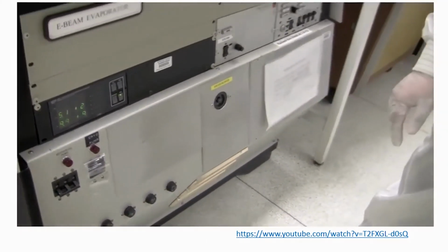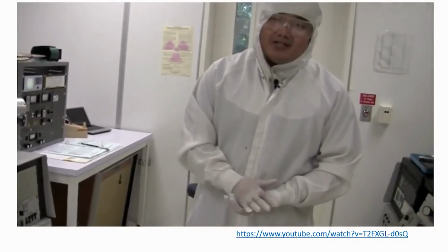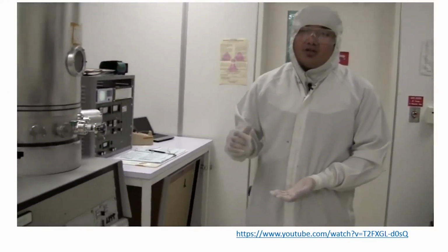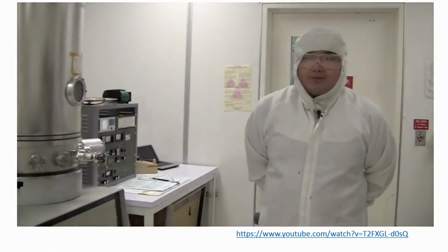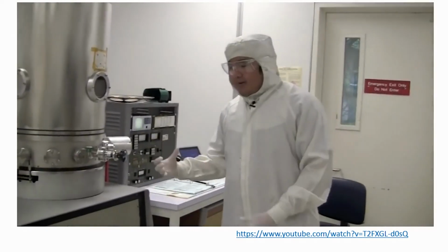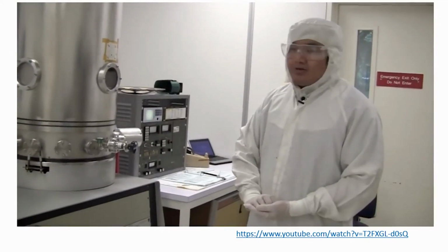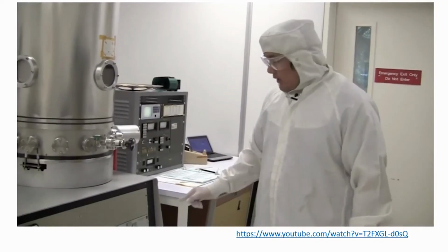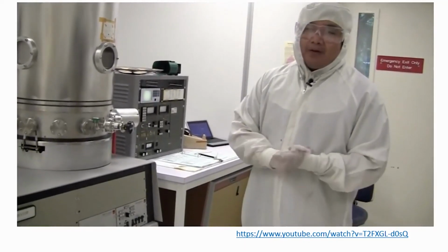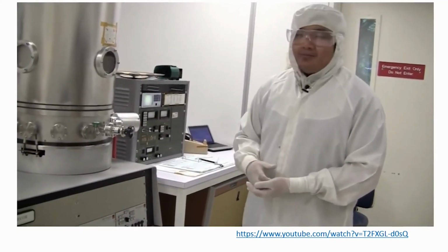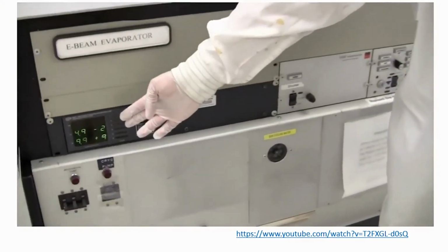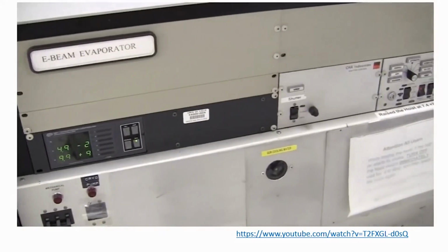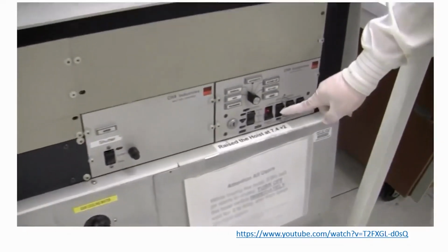We want to make sure that the pressure is less than 7 times 10 to the minus 2 before we turn the high vac on. But you can go a little even lower than that. So we'll wait a little bit for the pressure to drop. After the roughing pump has brought the pressure down to below 50 millitorr, we can switch the mechanical pump off for the roughing and turn on the high vac. So we look at the pressure, it's under 50 millitorr. And now we're going to turn the rough off.